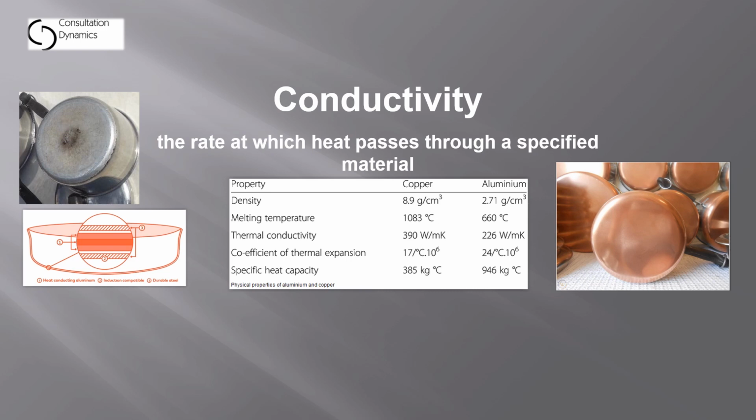If you were to compare copper and aluminum cookware, you'd find that aluminum-clad cookware usually has a thicker cladding of aluminum on it because, again, since aluminum isn't quite as conductive as copper, you need more of it in order to move the heat at an equal rate in order to get even cooking.